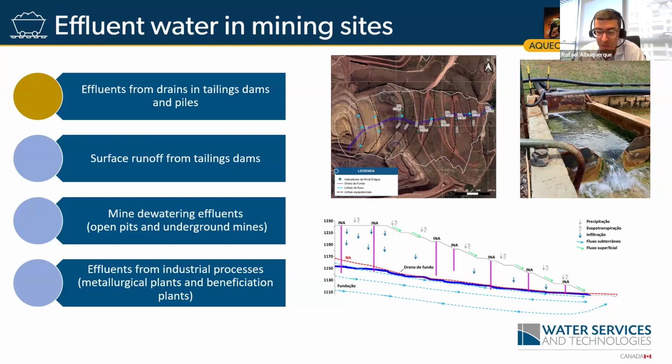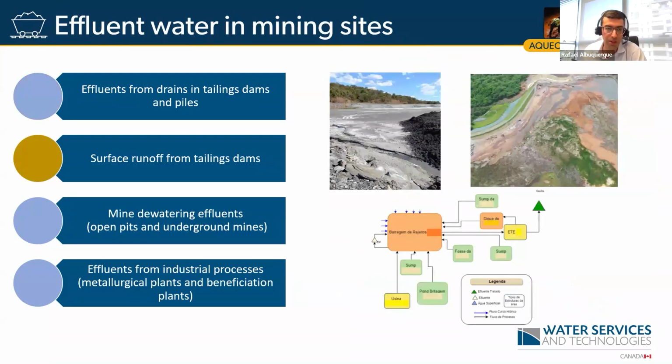But in terms of discharge rate, we are usually talking about hydrogeology. So the hydrogeology, the flow system within the structures: where is the flow direction, where is the groundwater level, do we have a saturated and an unsaturated medium in terms of piles, because saturation controls, for instance, oxygen dispersion into the pile and then the chemical reaction. So then again, we're talking about hydrogeology and classic acid and neutral mine drainage prediction.